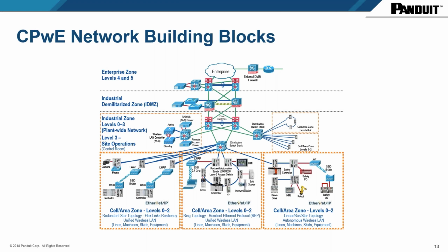They're two different worlds. On the factory system, the communication is real time. It's happening in nano and microsecond speed. When you go up to the enterprise, communication does not happen as fast and as frequently as it does on the factory side. So you separate those networks by a layer that we call the demilitarized zone. As you go up in the star architecture, you reach the central point here, which we call the data center space, the enterprise space.